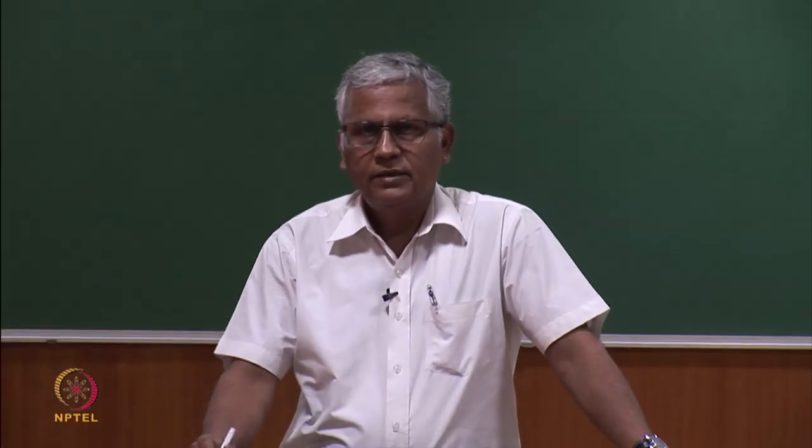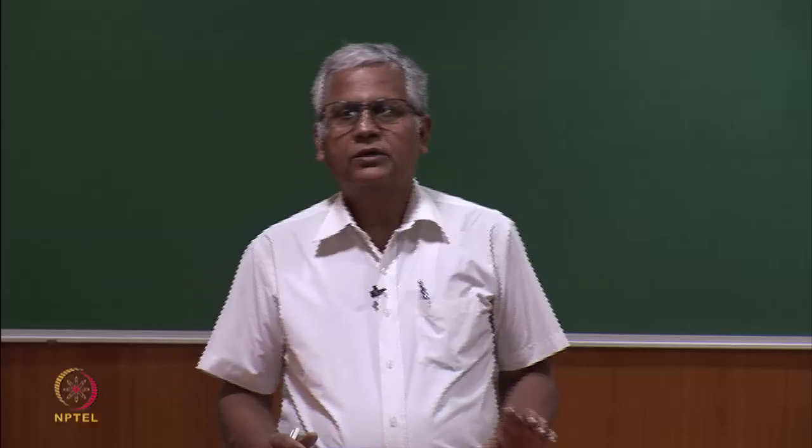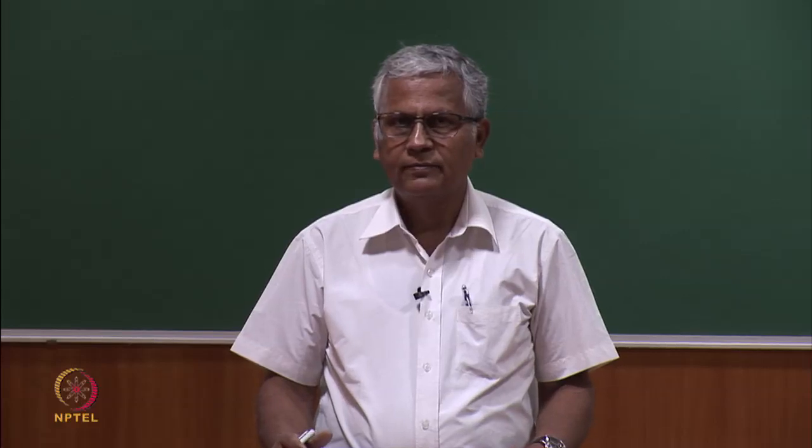That is, the left hand pole will disengage, the ratchet will be free and about to turn, it turns by half a tooth, and by that time the right hand pole comes on its way and engages with the tooth of the ratchet, and therefore is not allowed to turn beyond half a tooth.